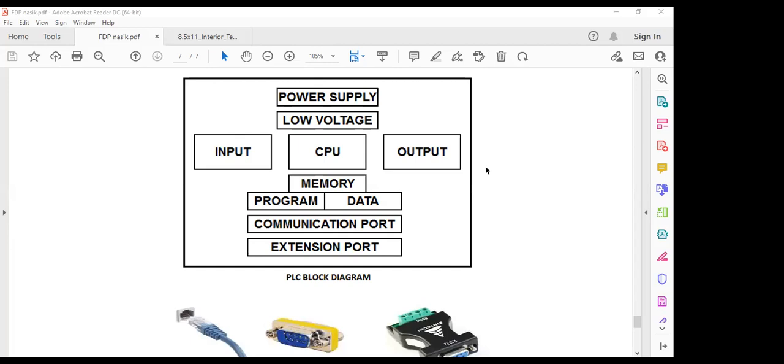It's not like for one rotation it will send you one on or off. For one rotation, it might send you 36,000 pulses. One rotation only, and you are going to 200 rotations or many. So in one rotation you are getting 36,000 pulses. That high frequency on-off signal, a relay won't take.